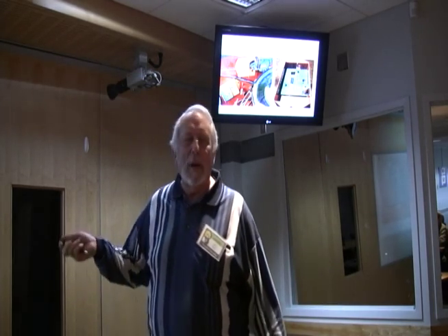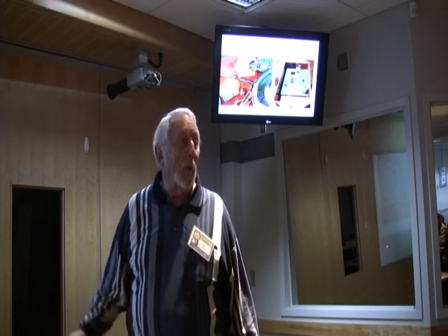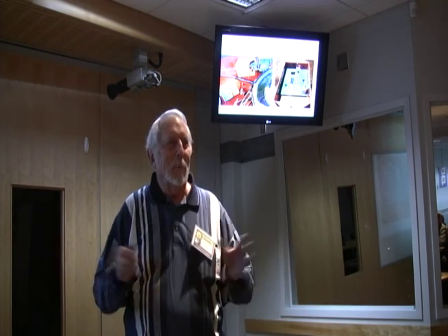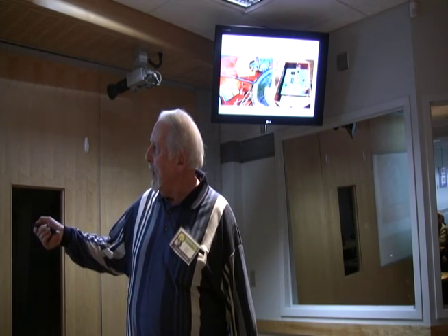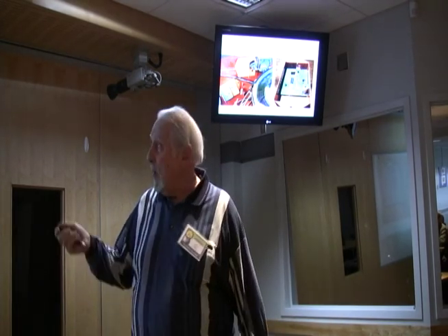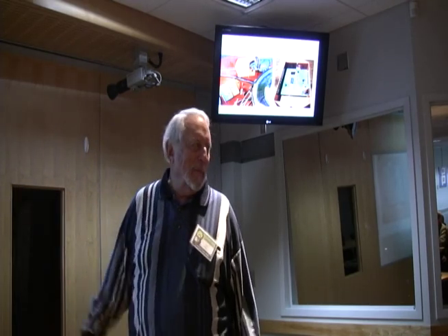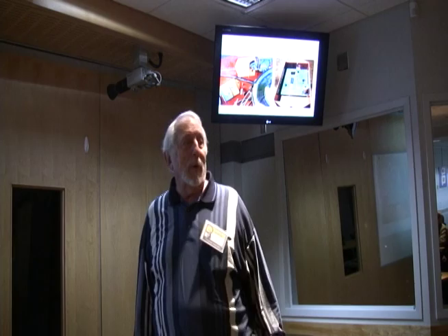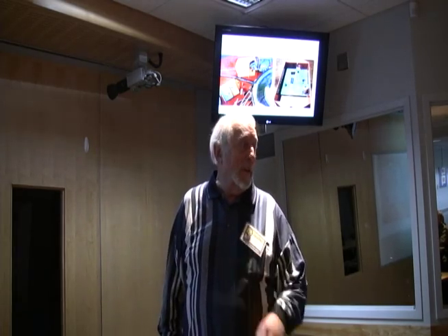But it only is there because Chrysler had a great big old RCA transistor right there. That was the points. That's what made the spark happen. Our part that makes that, the right part right here, is what makes the spark happen. It's embedded inside the system. And it's got to be cooled. So I cool it with a spring on the backside to the case. And you don't see that without taking it further apart. That was kind of unique. Put a metal spring in there to conduct the heat out of the chip. There's a hole through the printed circuit board underneath of it, so I can get right up against it with a spring.